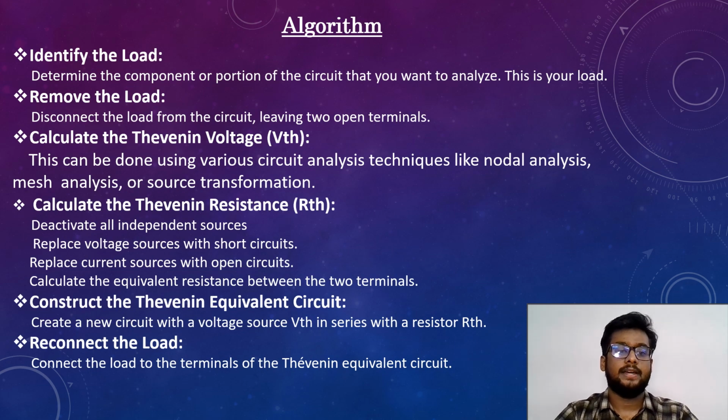Why is it useful? It simplifies the analysis, facilitates load analysis, and aids in circuit design. Algorithm. Identify the load: determine the component of the circuit that you want to analyze. Remove the load: disconnect the load from the circuit, leaving two open terminals. Calculate the Thevenin voltage. This can be done using various circuit analysis techniques like nodal analysis, mesh analysis, or source transformation. Calculate the Thevenin resistance.